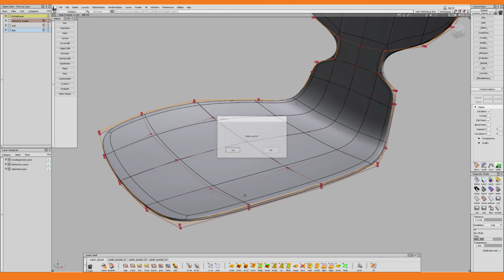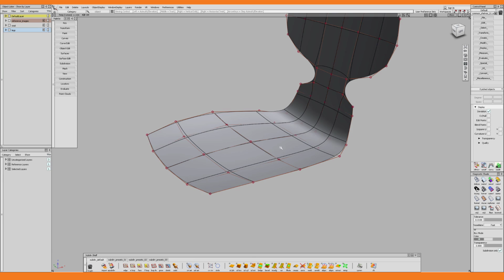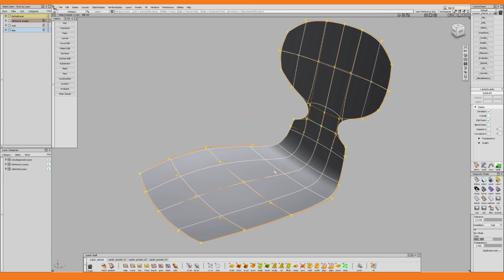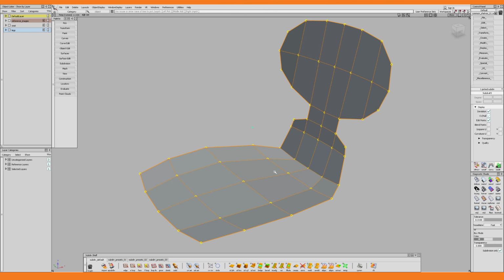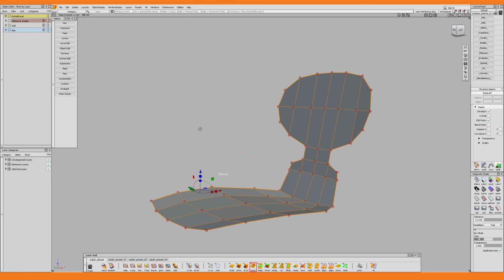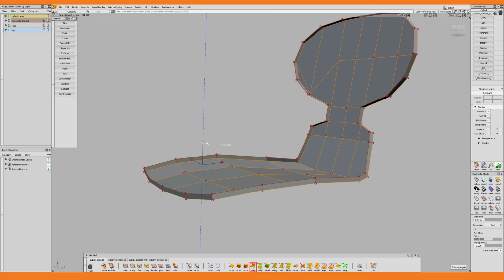Then I simply delete them. This splits the mesh into 2 separate objects, one of which I can delete. And now I'm kind of back to square one, just where I want to be. Before extruding, I once again make a copy of my A surfaces, which I hide. Then I proceed to select all the faces, and I go into the extrude tool. I set it to normal, and I make sure to make it a little bit thicker this time. So that should be fine.